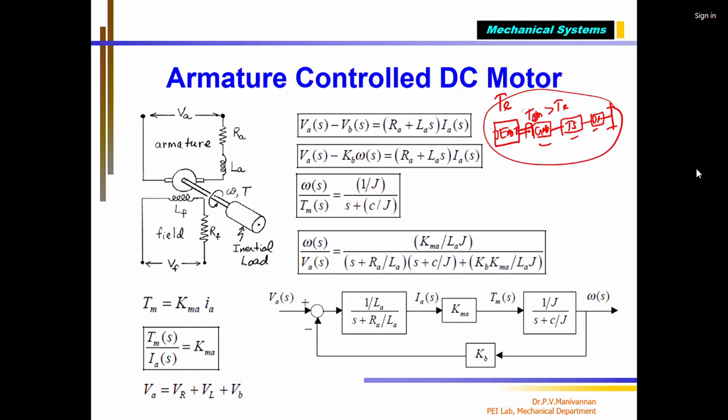Because everywhere there are losses. The produced torque at the engine, correct, maybe 100 Newton meter for your engine. Finally, available at the wheel maybe 90 or 95 or 85, correct? How much you lose depends on the bearing, the lubrication, the bearing design, all this matters. You want to reduce all the frictions so that all torque will be transferred directly to the axle. That is not possible. So not only engine friction, gearbox friction, transmission friction, differential friction, all this will consume a little of the torque produced by the engine TG.